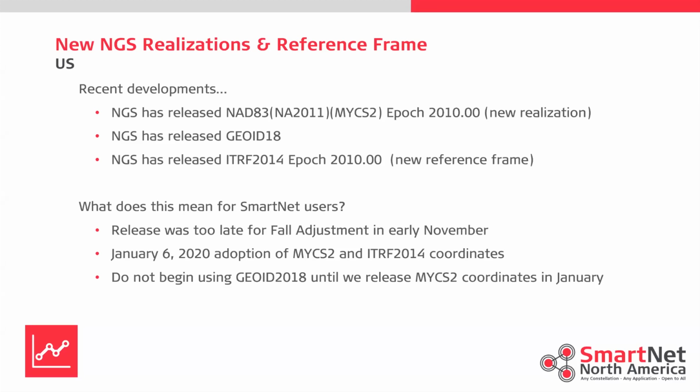And again, EPOCH is related to what date those measurements are referenced to. So these are referenced to EPOCH 2010. So we're not changing epochs in anything to do with the NAD83, but we are moving from an IGS08 2005 EPOCH to an ITRF 2014 2010 EPOCH. So these all make a difference.